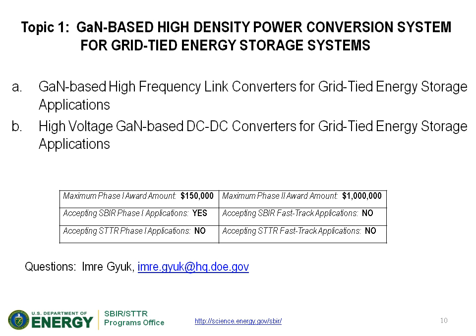In this topic, we're focusing on high-frequency link, where you take the 60 hertz transformer and push it into the power electronics, and now you have energy storage with a DC to DC converter with a high-frequency transformer operating at greater than 15 kilohertz. And then finally at the back end, a DC to AC direct-tied converter to the grid.